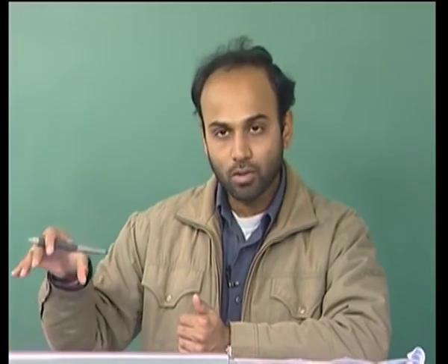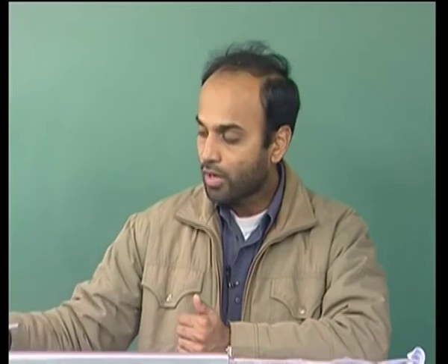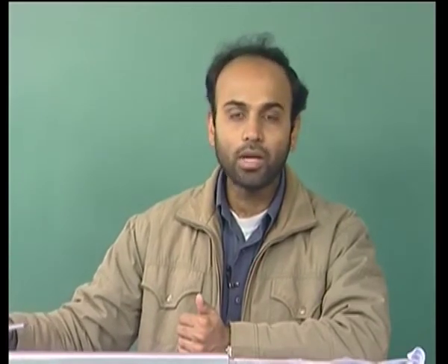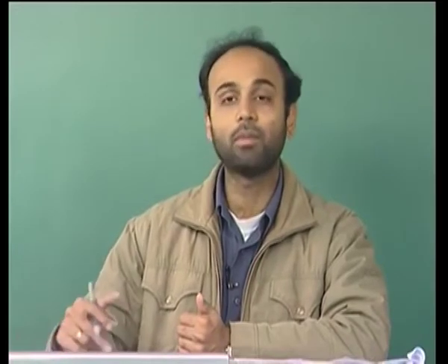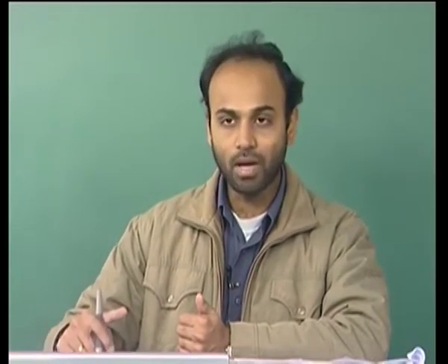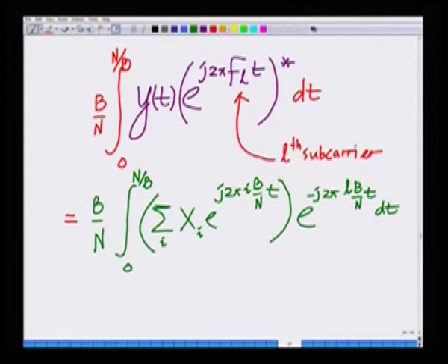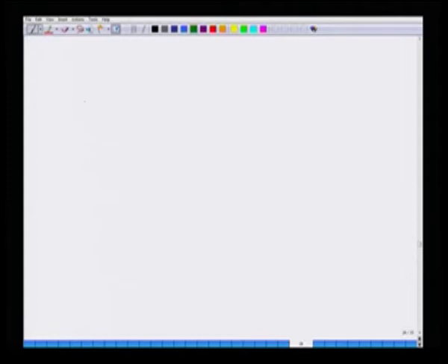I am taking this composite signal and correlating it with the lth coherent subcarrier, integrating it over 0 to N by B, and this B by N is a simple scaling factor. Okay. Now, let us see what happens in this scenario. I will take the summation out of the integral now, and this can simply be represented as